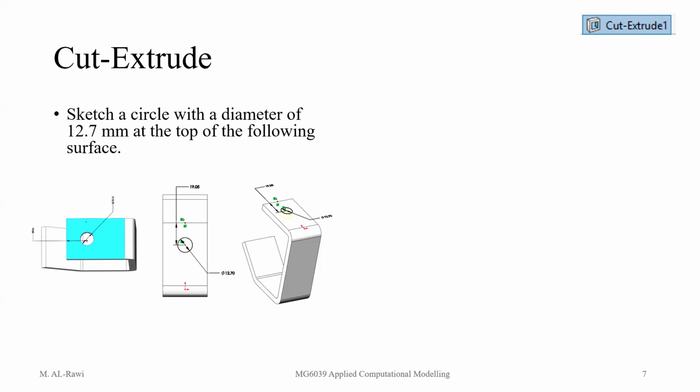You need to select the surface where you're sketching, because if you haven't selected the face, then we will not know where you are sketching. Yeah, and now sketch. Now select circle and follow the center line. Go down and put it somewhere, and then sketch. Close. Put the dimension.